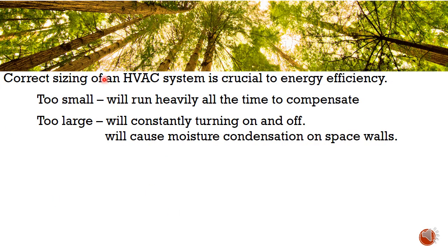So one thing that is very crucial to energy efficiency is actually the correct sizing of HVAC system. If the system is too small for the load, then it will run heavily all the time to compensate the load, and the lifetime of the components will be shorter.